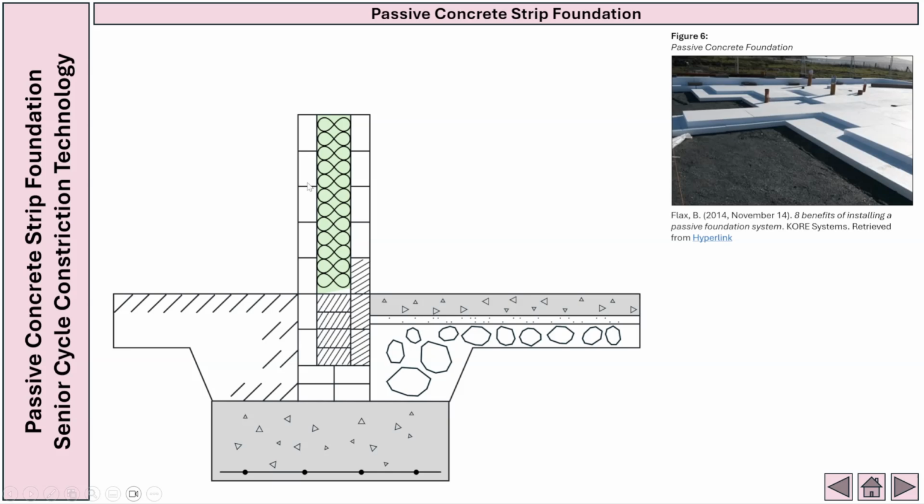We're going to start constructing the wall detail here. We have got our 100 external leaf, we then have our 200 insulation, and then we have 1 more insulated block followed by 4 standard concrete blocks. Next we have got our 80 insulation on top of our concrete subfloor, and then just beside that we have got our 150 insulation. On top of our 150 insulation we have got our 75 screed, on top of which then we have got our 25 flooring.